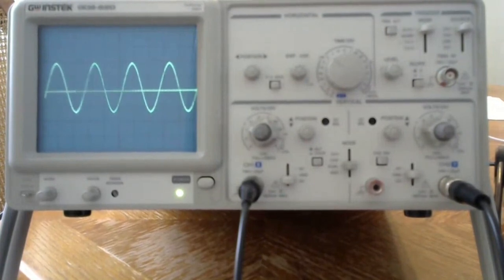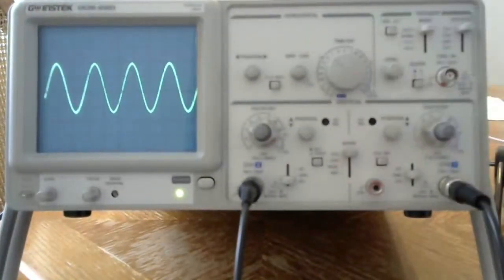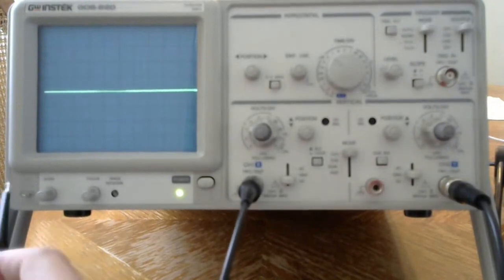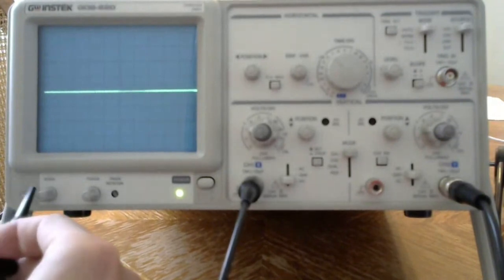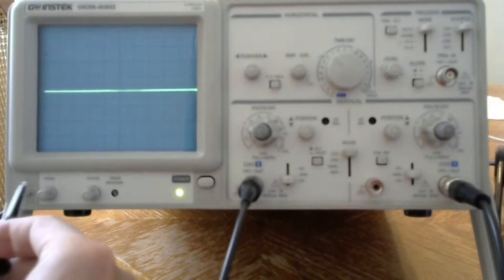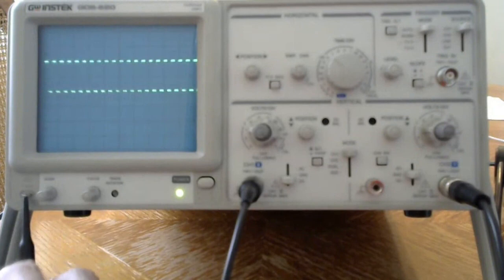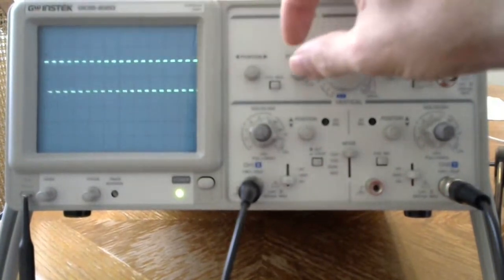One last thing I'm going to show you before I stop. I'm going to set this to just channel 1. There's my channel 1 right now. It's a sine wave. I'm going to remove my probe from my circuit, and I'm going to look at the built-in calibration. You can't read this probably, but what this says here is 2 volts peak to peak, 1 kilohertz. This is a calibration signal. If I put this here, I should be seeing a 2 volt peak to peak, 1 kilohertz signal. Okay, that's what I'm supposed to be seeing here.